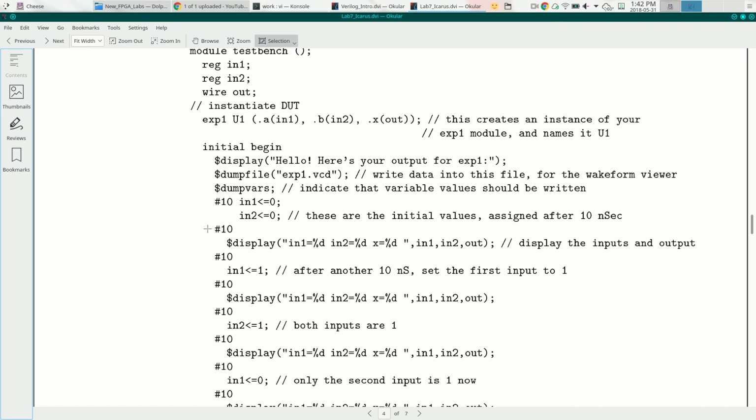The real issues come when you're trying to build a circuit that has maybe 50,000 gates inside it, and you're trying to put it on a device that has 60,000 gates available, so you don't have a whole lot of room to work with. You really want to use those gates very efficiently, so you want to do a lot of minimization, right? Come up with the fewest number of gates, but you also need to know what kinds of gates are available. If you've got a lot of AND gates, and your design really only uses a bunch of ORs, you'd like to do some De Morgan and change some of your ORs into ANDs, for example.